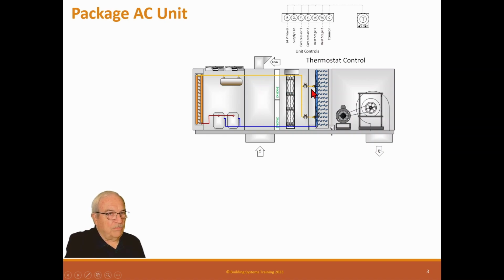But most of the time what happens here is they have a solenoid valve. And the reason they do that is that they have these compressors controlled off of discharge pressure. So when they want to stop this coil, they close the solenoid valve, but the compressor keeps going, and it keeps pressurizing the gas, and it fills up this receiver until it gets above a certain pressure, and it turns the compressor off.